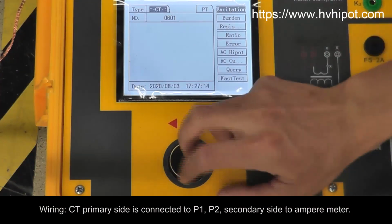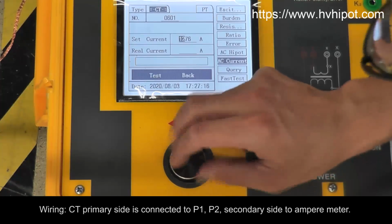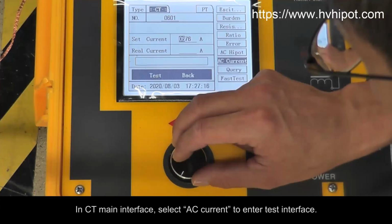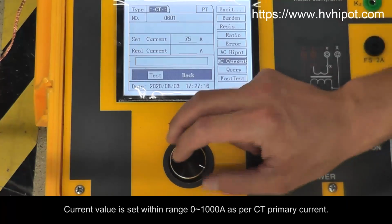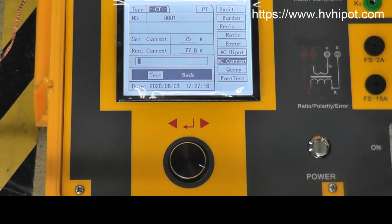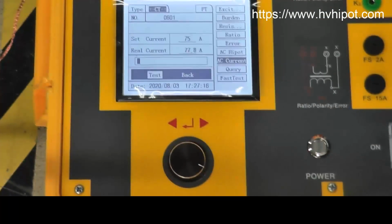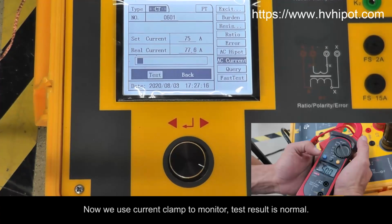Wiring: CT primary side is connected to P1, P2, secondary side to ampere meter. In CT main interface, select AC current to enter test interface. Current value is set within range 0 to approximately 1000 A as per CT primary current. After setting AC current, turn on power switch. Select Test, press controller to start testing. Now we use current clamp to monitor, test result is normal.